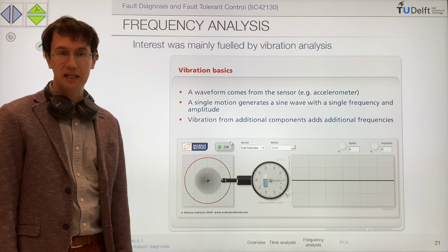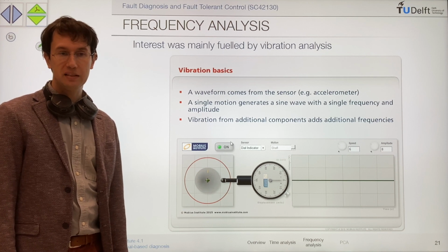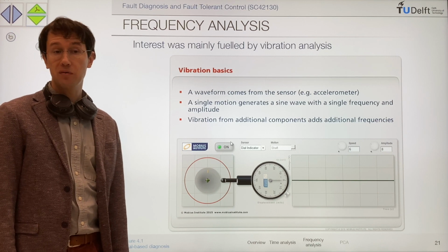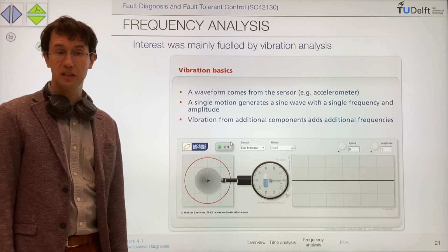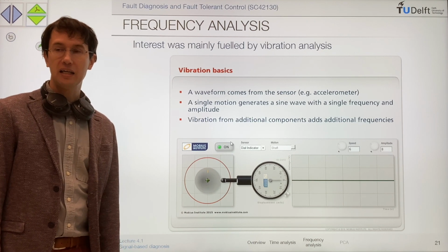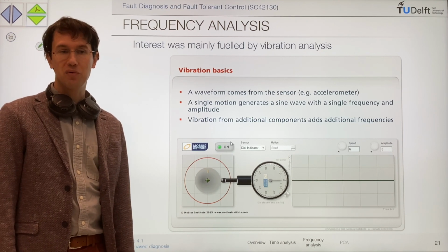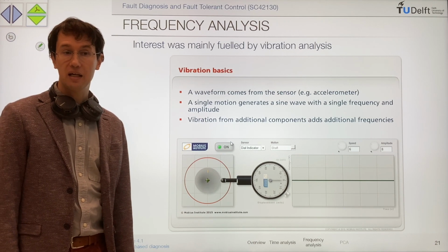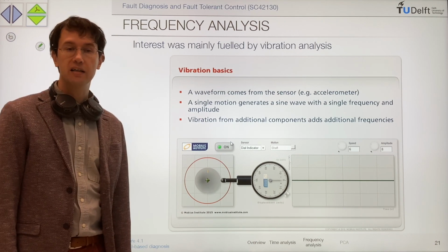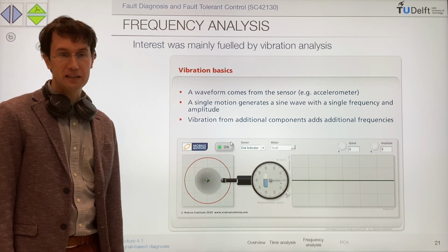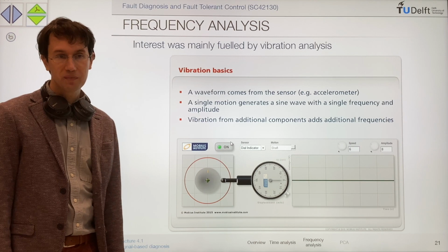is some baseline normal pattern in the frequency domain, where you have a main component corresponding to the rotation speed of the machine and other components corresponding to the rotation speed of other axles that you can have in the machine. But everything else should not be there.